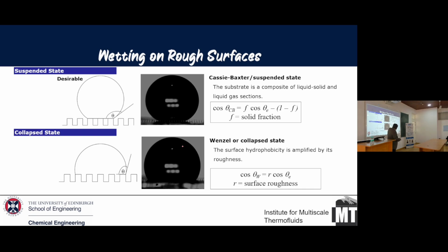Okay, and this is one of the formulas, one of the approximate ways one can determine the contact angle of this substrate. So what is FTS? A solid fraction, the area covered by the solid. So basically these bits are not covered by the solid at all, but these bits are. So it's the extent of fraction.